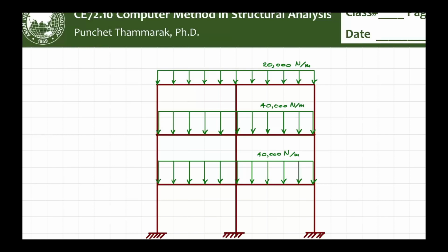So if you do it in the evening time or maybe late afternoon, you pour concrete, and then sunset, it's not too hot. If the weather is quite dry, then after the concrete gets hardened, you spray water on the surface. In the first day, you need to spray a lot to make sure that concrete gains strength before it suffers from plastic shrinkage. And then you get a very nice roof slab, and that's going to be long lasting.